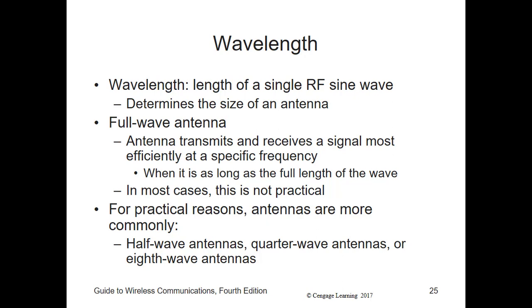So an AM station antenna, for example, could be built as a quarter-wave antenna at about 464 feet as opposed to the 1,800 feet, which is still large. And the cellular antenna, using the same ratio, could be 3¼ inches long, which is about the size of your smartphone today.